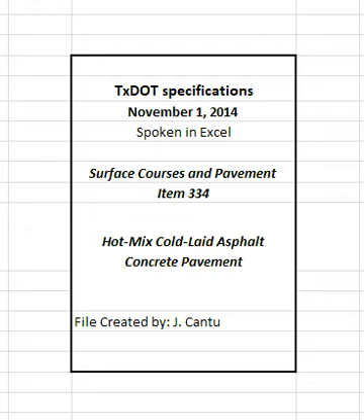Document all test results on the mixture design report. The engineer may perform tests on independent or split samples to verify contractor test results. Stockpile aggregates for each source and type separately. Determine aggregate gradations for mixture design and production testing based on the washed sieve analysis given in Tex 200F, Part 2.